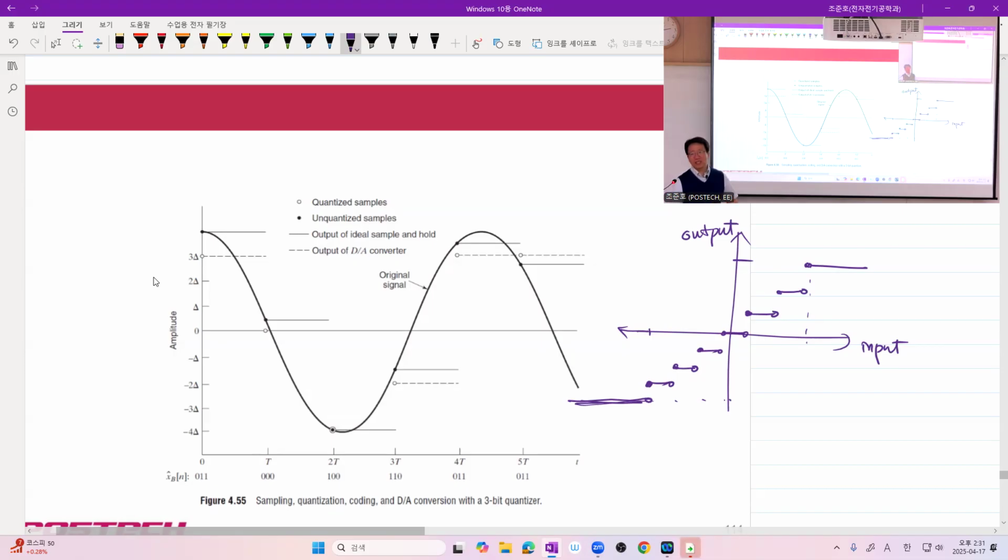And most of the textbook says this way, but actually it is not true. Okay? There are many other methods. The first thing is, what about the spacing between these outputs? First, they could be the same. Second, they could be different. And when they are the same, usually it's called a uniform quantizer. Which means non-uniform quantization is possible. And you may wonder when we need that.